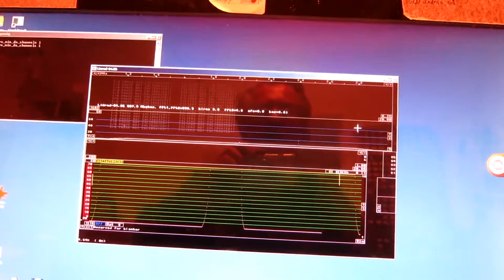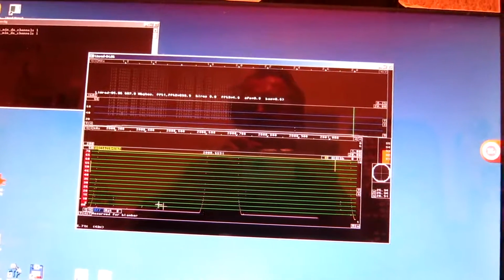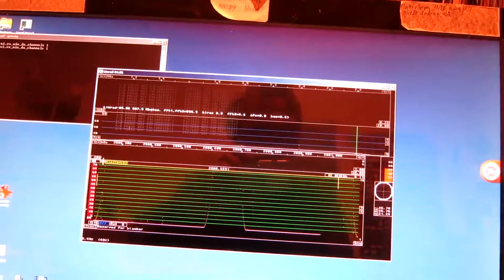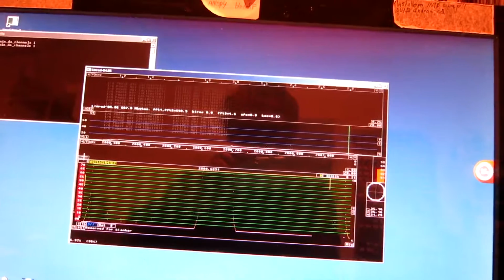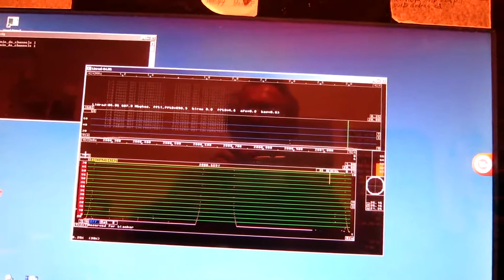At the very low sampling rate for the baseband that I have now defined, 100 seconds is not a big memory. Now when I click on the signal here, I have to set the averaging very small, because now transforms span a long time.